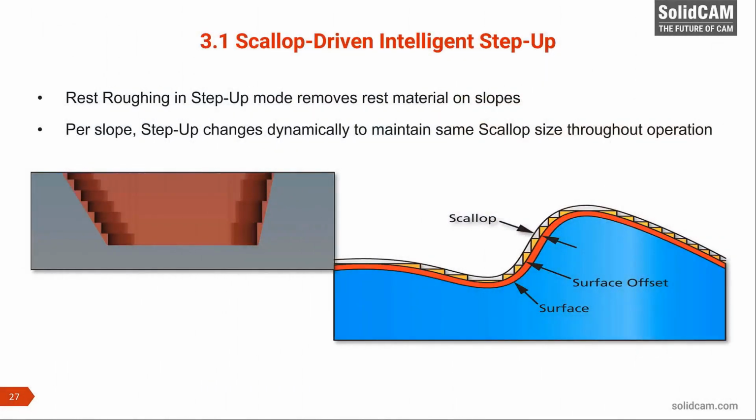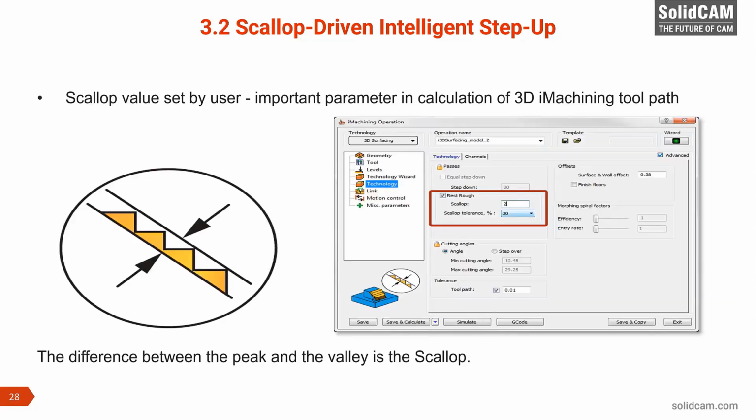iMachining 3D not only produces extreme savings in roughing cycle times, but by using step-up scallop height calculations, it can leave the model in a true pre-finish condition, ready for the final finishing operations. You see, these Z-steps are calculated based on surface inclination angle to achieve a constant scallop height, further contributing to stabilizing the force load on the finished toolpath, even though that toolpath comes after iMachining.